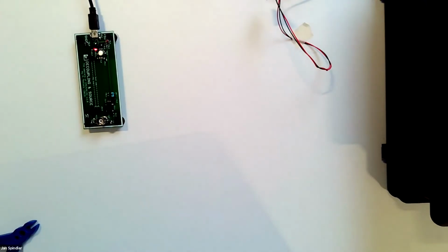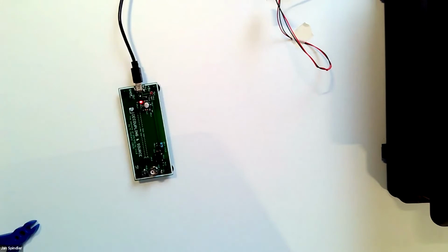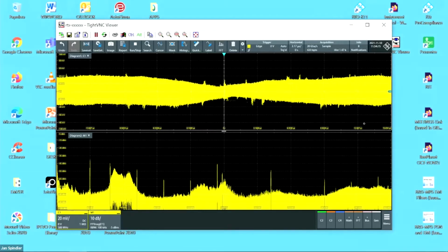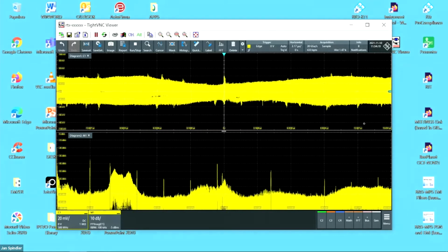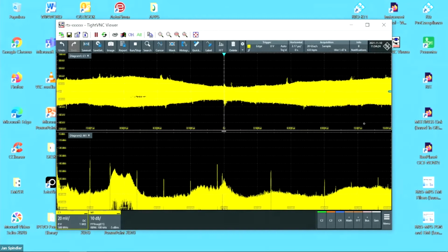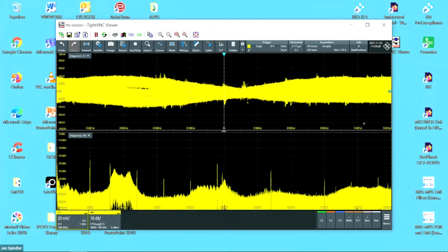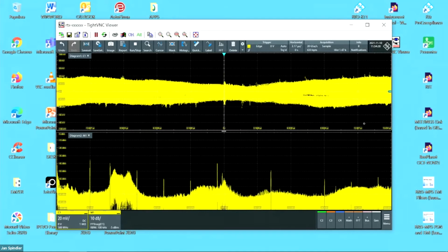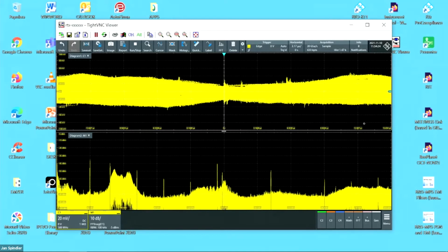Okay, this is my PC board, and this is what I get in emissions. You see that now I have less broadband activity, because the buck converter is off. I have a power adapter, so I have some kind of broadband emission that is lower, and you can see the peak. Consider that this is the peak that is important for me. I am over the limits in that peak.